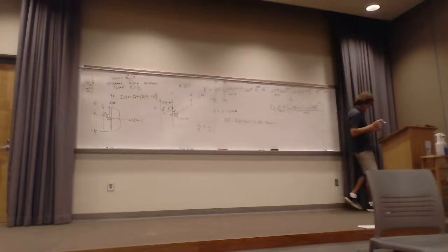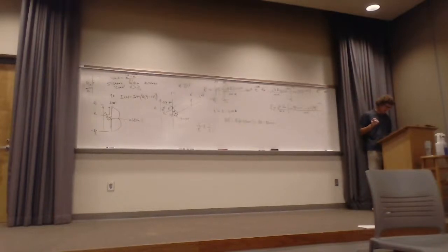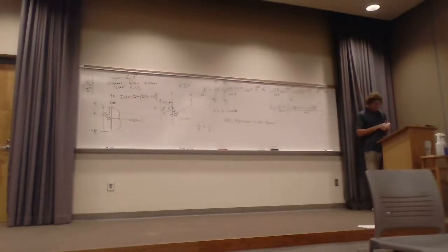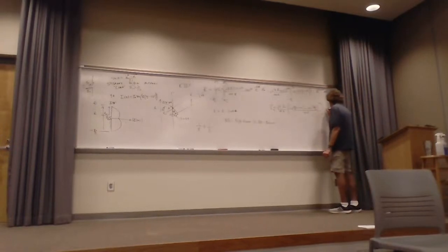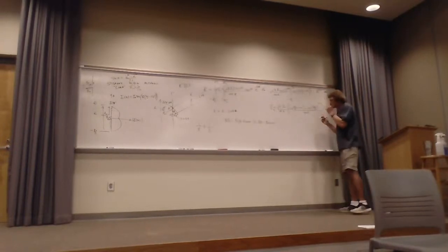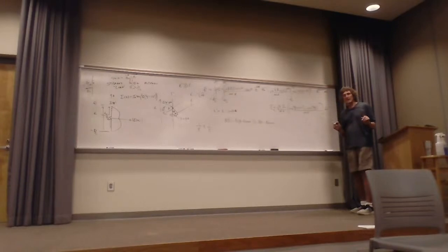He has that angular form in equation 8.71, and he has a square of that in 8.47. Now that's after you do the integrations, and this is in the A theta direction. This is assuming that the antenna is aligned with the z-axis with length L. Y'all with me? Here in this one, the L is the length of the antenna.